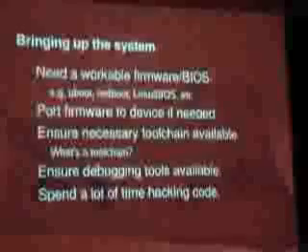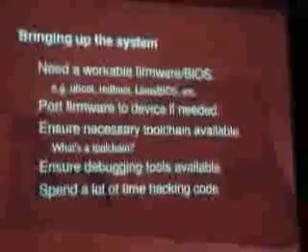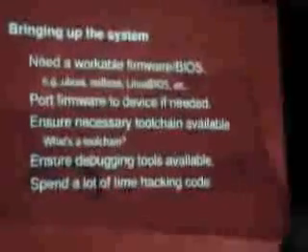So I have a piece of code. The reason I have a BIOS, the reason I have Linux BIOS, U-boot, Red boot, one of these things running. On a PC, I'll have a regular BIOS written by one of those companies you see when you turn your PC on. The reason you have that is your machine does not know how to properly talk to its memory, how to properly take advantage of a lot of the fundamental features it has until after they've been set up. Yes, it can load some code and run it, but can't do very much until this piece of code has come in there first. This piece of code also may support more than just getting the memory working, getting caching support turned on, these kinds of things.